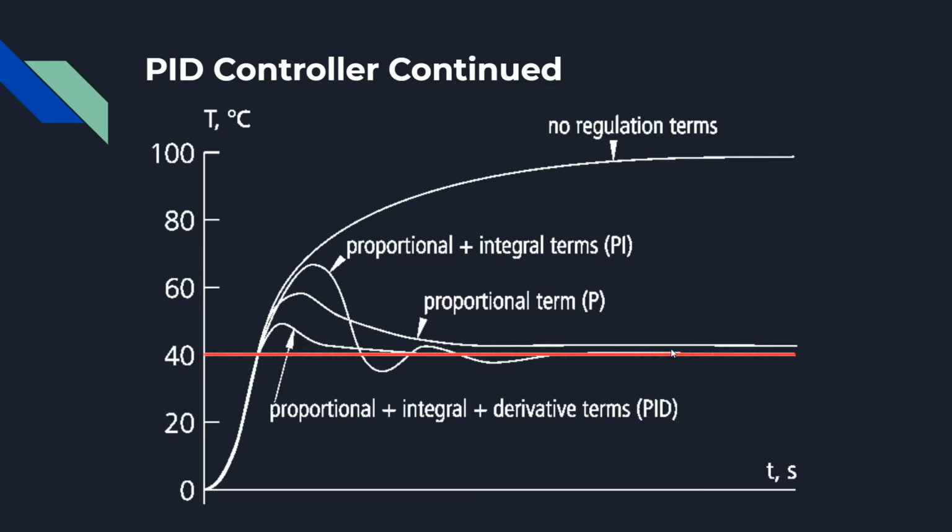If you try getting out of this, there would be an error which would be added, and it would come back down to the final steady state. So we'd actually get zero final state error. Steady state error is what we call it. So there would be zero steady state error if we were using a PI. But the problem is, here we reached the steady state pretty soon, whereas with a PI controller we reach the steady state much later, and there's a huge overshoot.